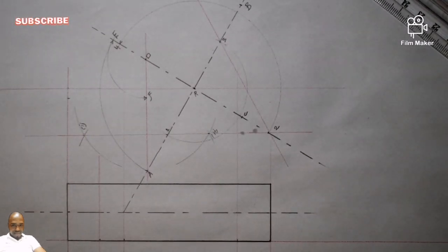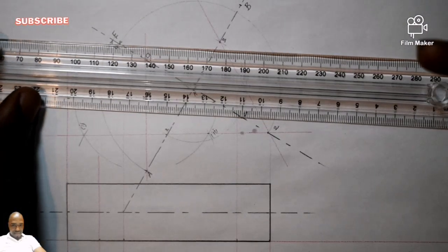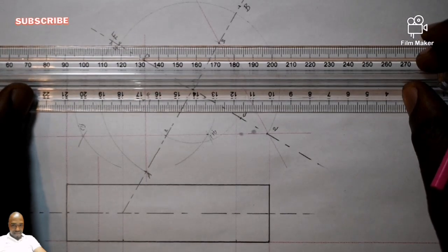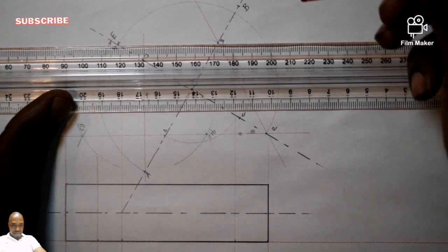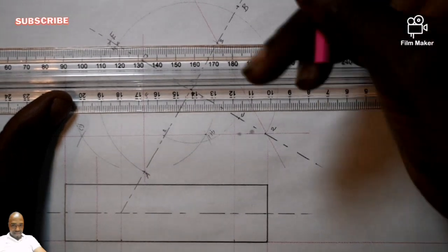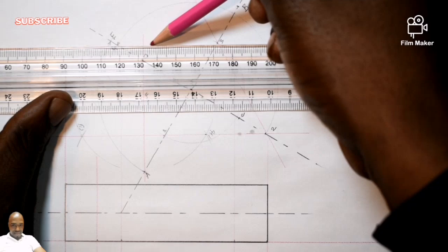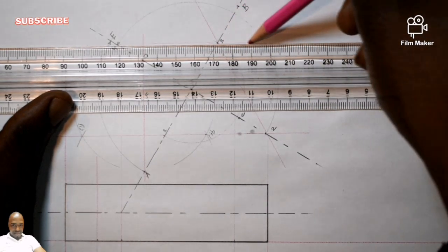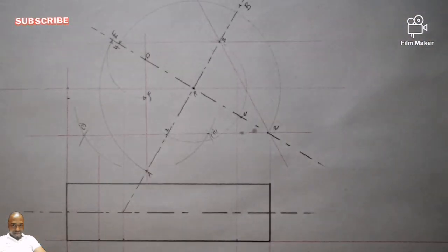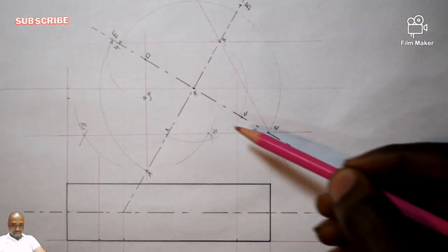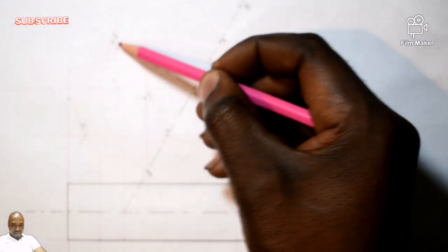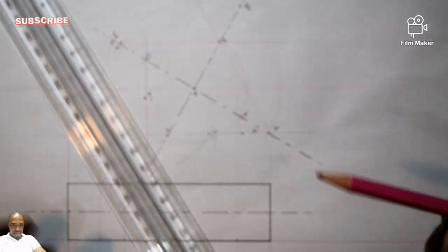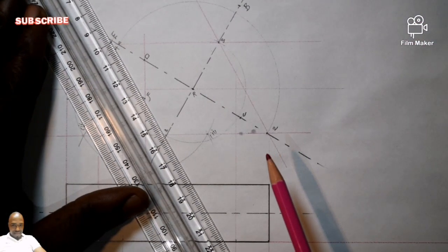You understand? So now take your 30mm ruler, join point 4, which is what you just got, with 3. Using your 30mm ruler, be accurate. So there you go. You don't stop here. Extend it a little bit. There is a reason for that, my brother. So now we have 1 to 2, 2 to 3, 3 to 4, and supposed to be 4 back to 1. Constructional lines.